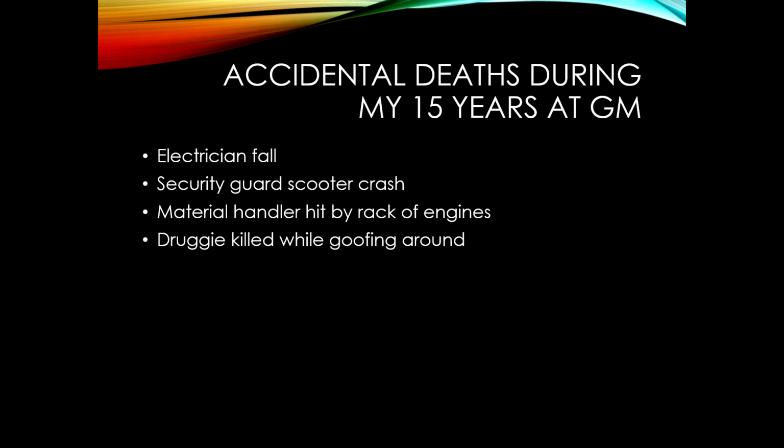So we had a station where operators could wipe off the bodies with some kind of solvent, and then the body would go into a tunnel and go through a long acid bath where nozzles with acid would totally clean off all the solvents from the body. Then when the body came out of that tunnel, it was ready to get primed and painted.